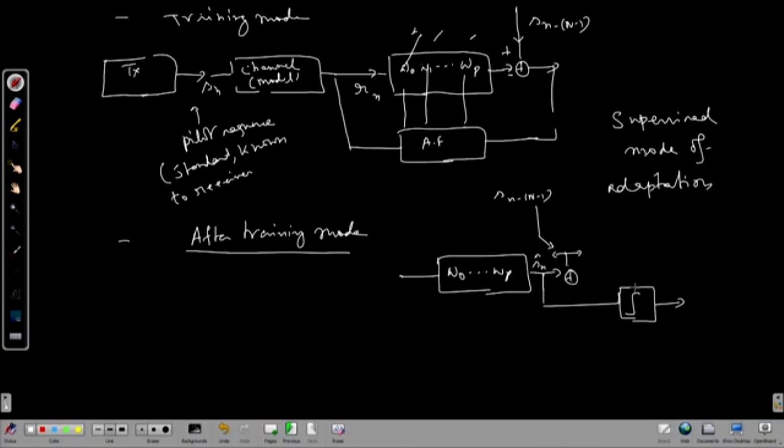but Sn cap will then be passed through a quantizer. Quantizer means I know what was transmitted were discrete levels, either this value of voltage or that value or that value, nothing in between. So, on this scale maybe I have either this or this or this, and around each I have a band.